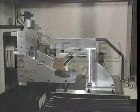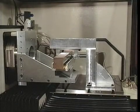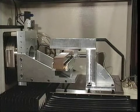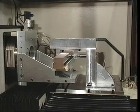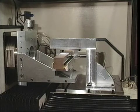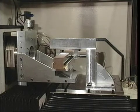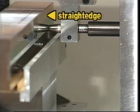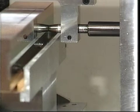Using the reversal technique and some basic hardware, straightness measurements will be made for both the reference straight edge and 225 millimeters of the x-axis carriage travel. A metal-plated Zero-Dur optical straight edge will be used as the reference.